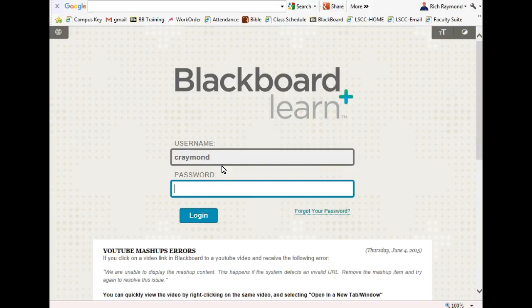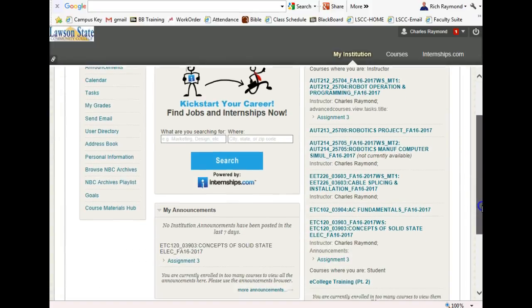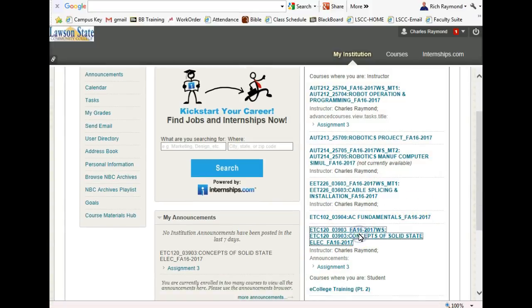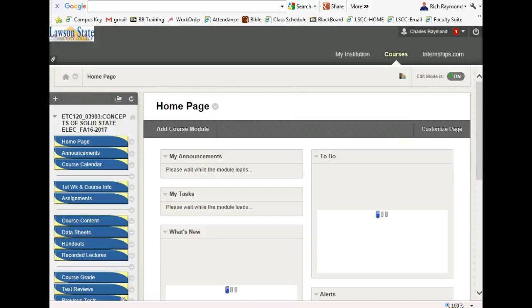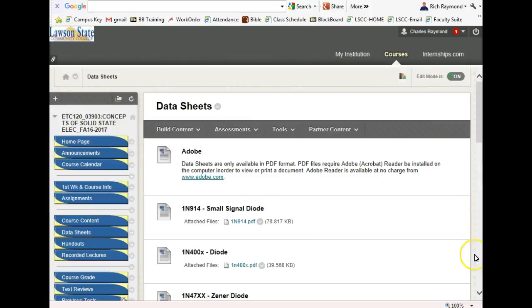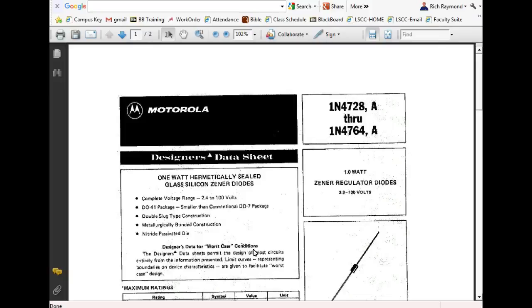I guess I've been in the field quite a long time, and I know when we've got a problem and when we don't have a problem. But I know what Zeners I'm using. I'm trying to use the 1N4748. Well, on the very first page of the data sheet on the Zener, one of the first things they give you is the wattage rating on the Zener. If you exceed the wattage rating, what's going to happen? You're going to mess up. So I'm going to look at this 1N47. It's a 1 watt Zener. Our design is going to require how much? 2. So what does that mean?